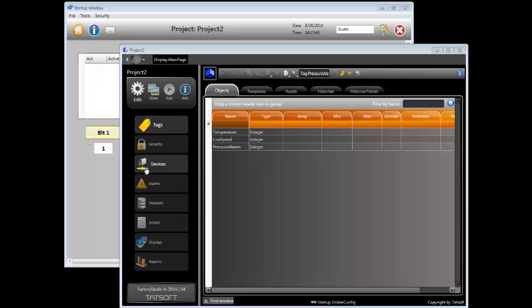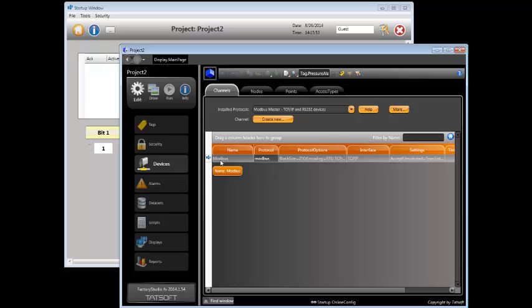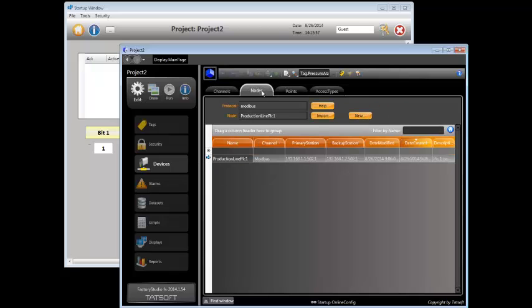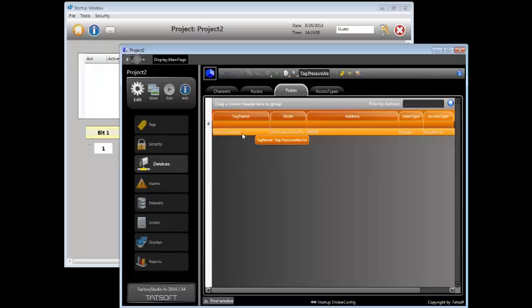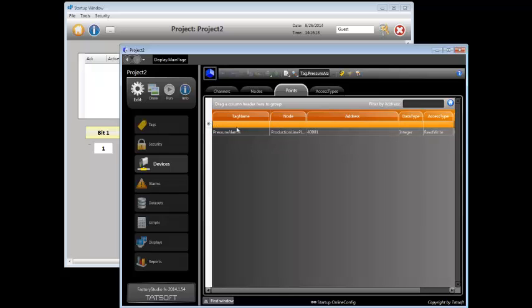We're going to use word address number 40001 in the Modbus protocol. To do that, we go to Devices. We enable the Modbus protocol. You define a node, which is a PLC, which the data will be coming from. It's at this location here under Edit Devices Points that you define the PLC address that is going to be linked to a tag.